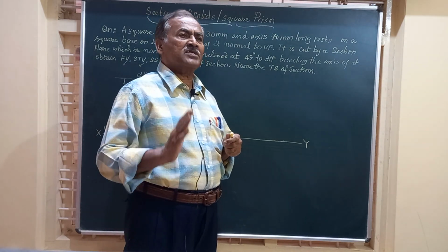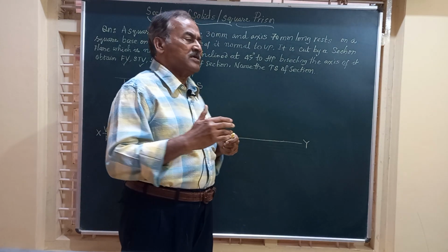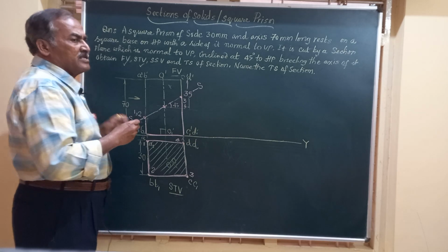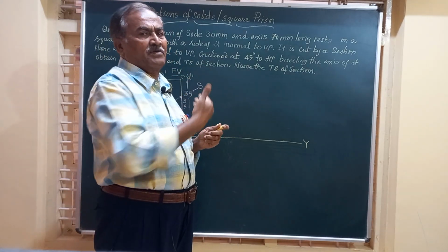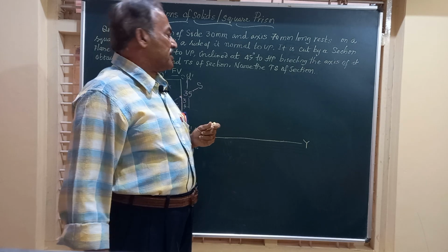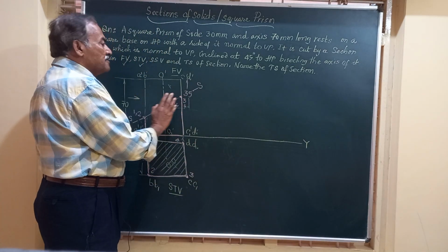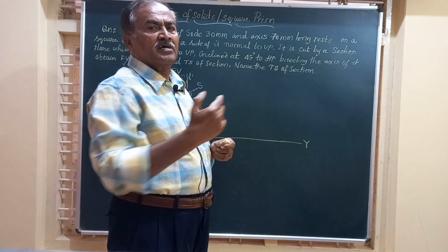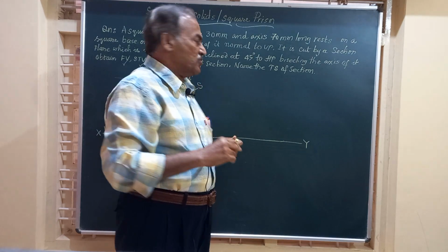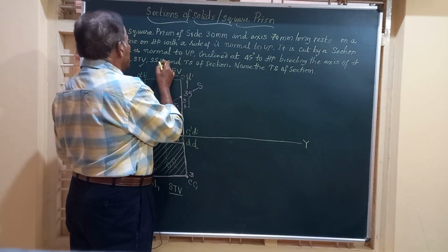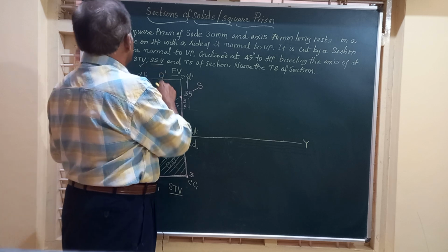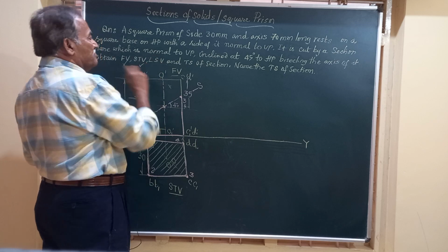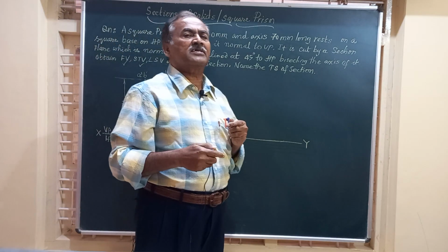That is, how does the object look when the upper part is thrown away and it is viewed in the left direction, from the left end of the observer or to your left. Friends, what happens when you see this object from this left end? The image of that falls on the right profile plane. So the left end view which you are going to get, the left hand view, or you can say left side view, LSV, is obtained on the right profile plane.